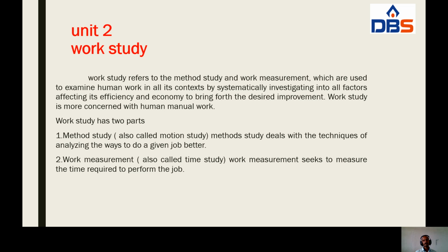Here, work study has two parts. The first one, method study, and the second one, work measurement. Method study is also called motion study. Method study deals with the techniques of analyzing the ways to do a given job better. That is the meaning of method study.